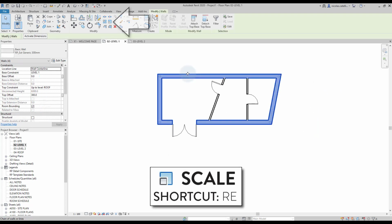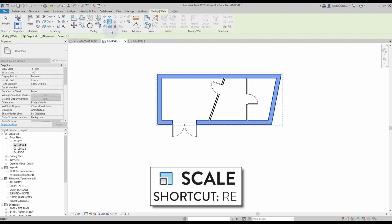Select the Scale tool in the Modify tab or use shortcut RE. The best way to use this tool is to use the numerical option. Enter a scale value in the option bar. Simply click on the view to complete the scale effect.